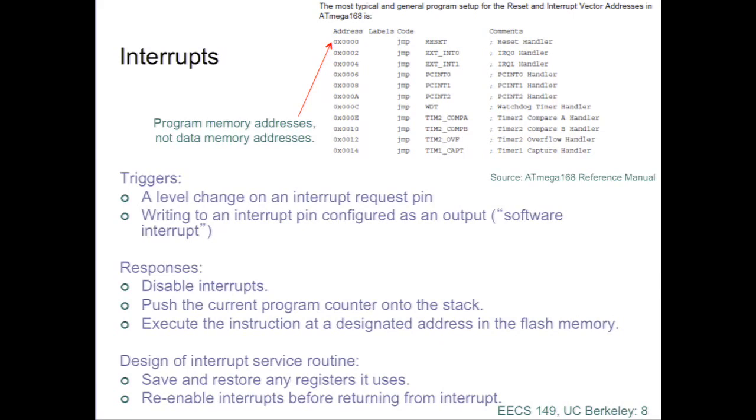That's actually a pretty important thing to understand when you're in a memory-constrained embedded system environment and you're worried about stack overflow, right? Because I think in the last lecture when I was talking about memory models, I was saying, well, if you have a procedure that has an integer argument, that's going to get pushed on the stack. That's 4 bytes on the stack. If it has an automatic variable that's an integer, maybe that's another 4 bytes on the stack. So your stack pointer is going to get pushed by 8 bytes. But it might get pushed by a lot more because the compiler is going to push a bunch of state onto the stack as well. And unless you know the inner workings of the compiler, you have no idea how much that procedure call is going to push down your stack. So stack overflows can occur very easily by accident, even if you're being very careful about the code, because whether a stack overflow occurs ultimately depends on details that are not very visible to you, right? You don't see how the compiler works.